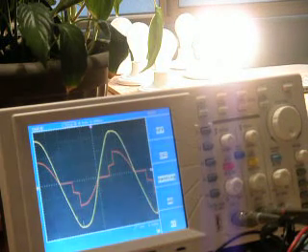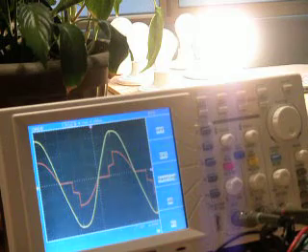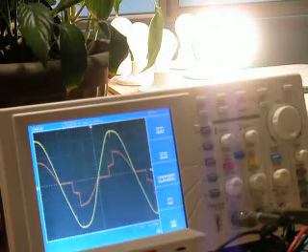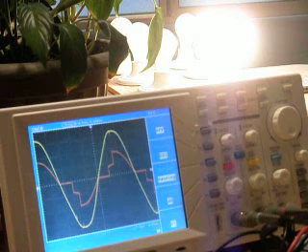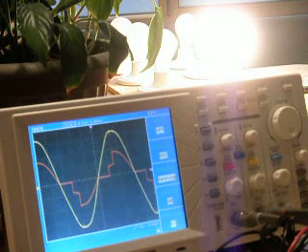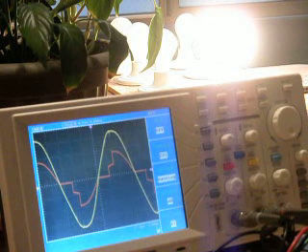So you can see with two lamp dimmers on, we have a very distorted current waveform, and it's stepped. So it's partially digital with that digital switching of the light halfway through the waveform. And that creates a lot of really bad noise on the system. And it gets even worse when you put the third light bulb in.